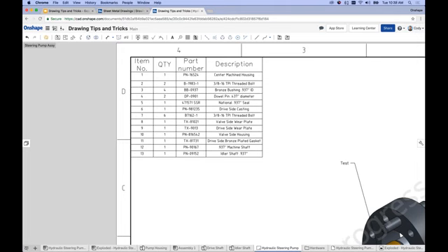When using a hole callout for a stack of holes, hole through one piece and tapped and terminated in a second piece, the callout displayed is the same for the wrong part. This is the same question as earlier. The callout is going to be the same. So if you have a hole that goes through three different parts, and the first part's a counterbore, the second part's a clearance hole, and the last part's a tapped hole, as of today, I'm 90% certain the callout is going to be exactly the same, and I think this is the comment that's being made. And if that's the case, please let us know. I think this has been reported by others.